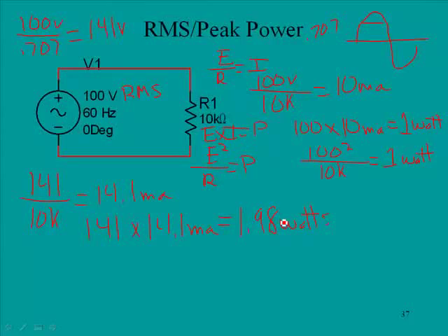So be very careful when you evaluate the power on amplifiers and whatnot, because in this particular situation, say we amplify it 100 times, and so here you've got a 100 watt amplifier rated in RMS, and then there's another amplifier that says it's 198 watts, but this is in peak, and technically if you do the math, they're the same power. So anyway, this is a discussion related to RMS versus peak power.